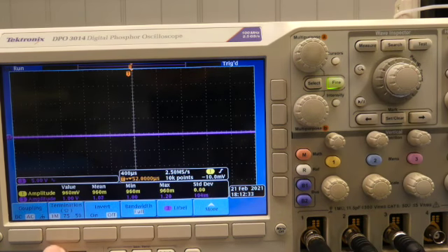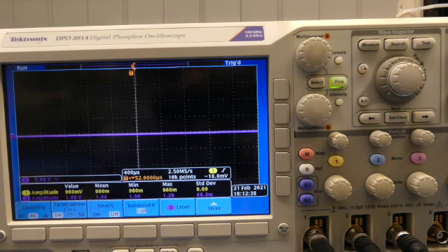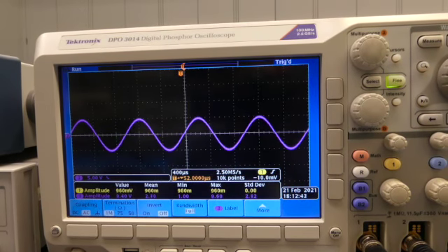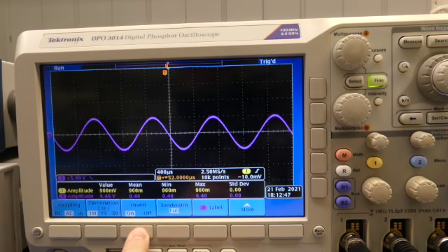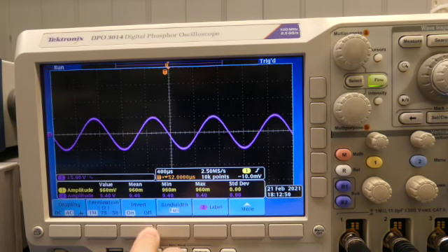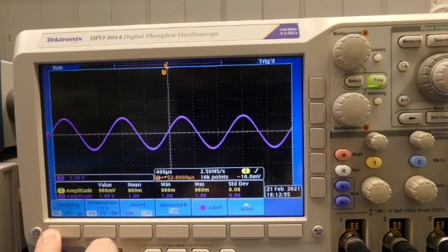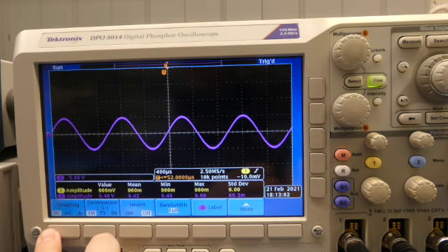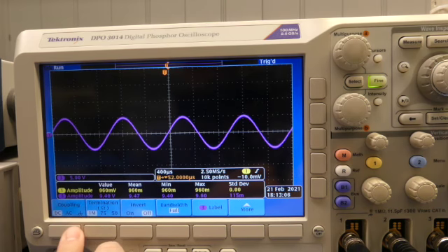Next, we're not going to worry about termination. Invert. It inverts your signal. It flips it, which I'm sure you can imagine what that's like, but I'll just show it right here. It's inverted right now. Oh, yeah, see, look. Invert is on, invert's off. It's also AC coupled, so it's right in the center. But there's going to be no difference on this one, in this particular case, between DC and AC coupling, because there's no DC component in the output here.